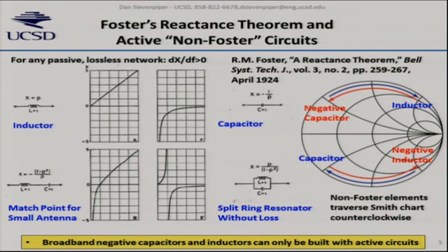So, for example, a series resonant circuit, that looks a lot like many small antennas that you might build. The reactance can be 0 at exactly one frequency, and you can see the reactance goes very high, positive or negative, at other frequencies. So the antenna is really only efficient right around that one spot. You can also see, for example, this parallel resonant LC circuit. You can, again, get positive or negative values, but the slope is always positive with frequency.